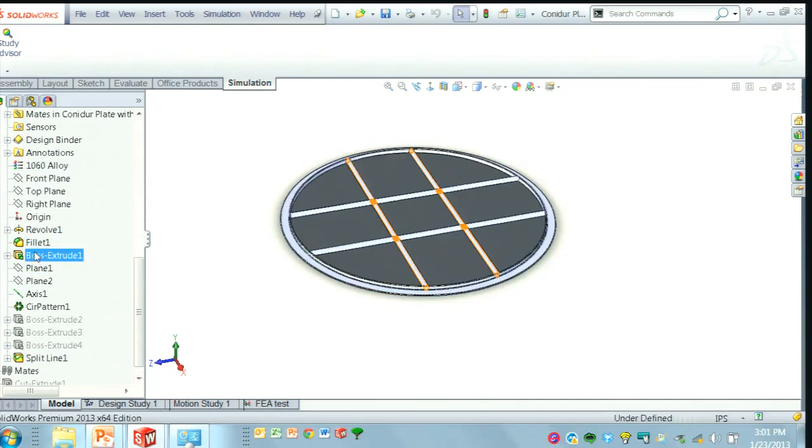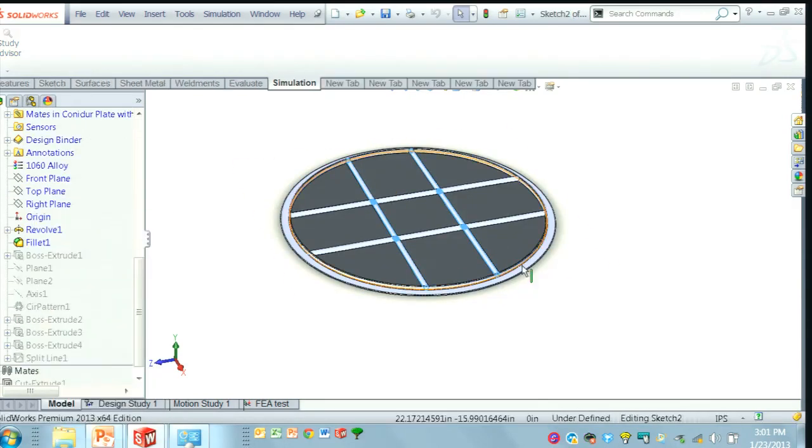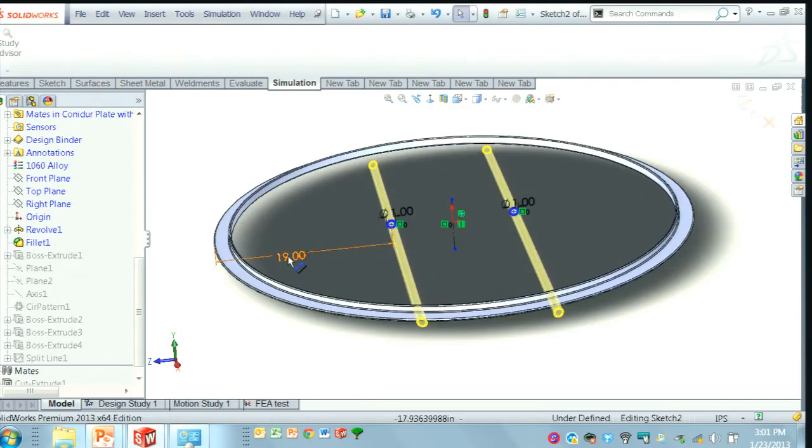So if I look at the sketch, the only real thing that I need to adjust here is this 19-inch value, because the way I modeled it, the two bars are spaced out, and then I do a circular pattern for the next set of bars. So pretty simple. If I create an optimization analysis where I'm optimizing that 19-inch value, I can have it spit out a result that's maybe something I wouldn't have thought of, or I didn't want to take all the time to check all those different iterations.